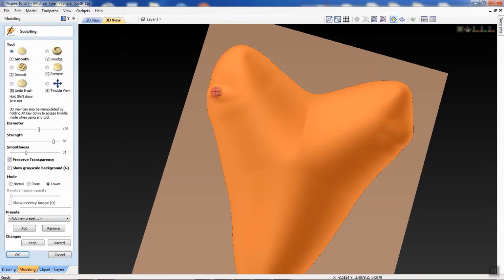Now, because I've got this set at the extremely high resolution, it does affect the way that the sculpting tools react with the model. There's a lot more pixels there it's got to process when you're at these higher resolutions. If I had a standard or a very high resolution, which is lower than the extremely high resolution, then the sculpting actually responds differently and quicker than when you're using sculpting tools with the higher resolution settings.